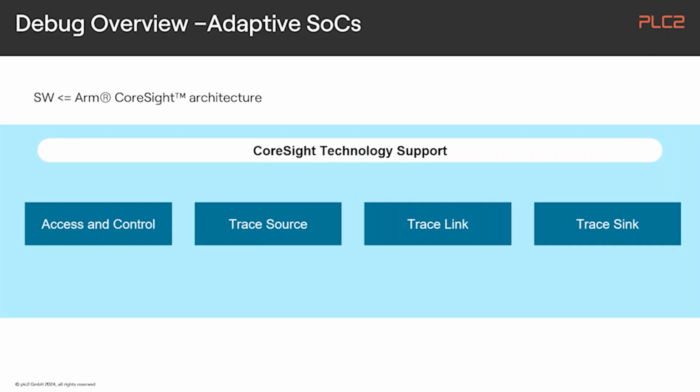With ARM technologies, the CoreSight architecture of ARM is seen inside of the processing system. And this can be connected to debug ports, mostly used with a USB cable, but actually also even more interfaces as far as wider data throughput, high bandwidth are required.